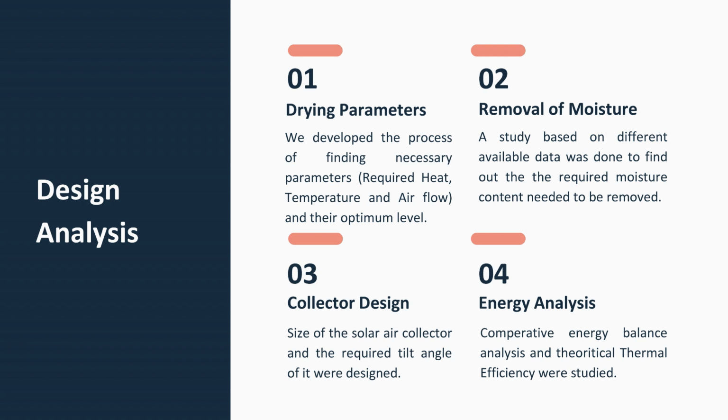Our initial step was to find out the drying parameters. We developed a study to find out what our required parameters are, such as the required heat, required temperature level, and airflow, and what is their optimum level for drying the paddy we are using as a sample.